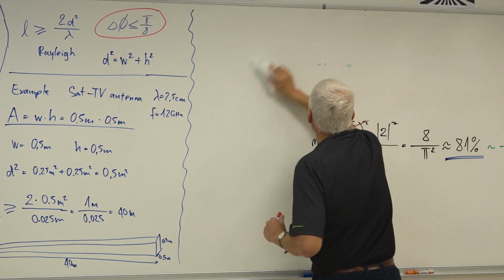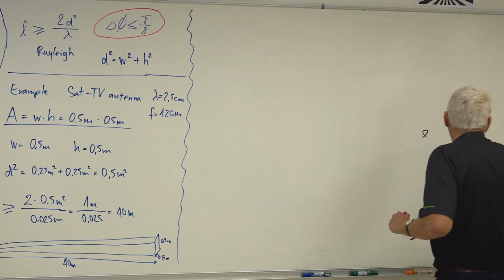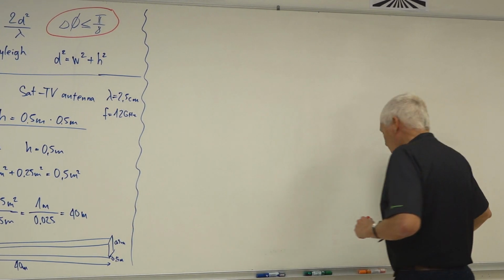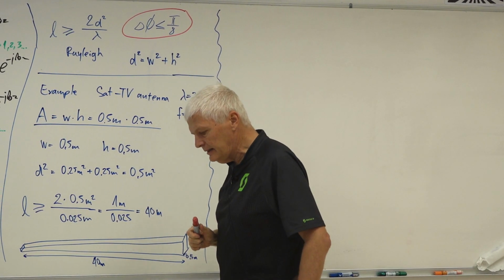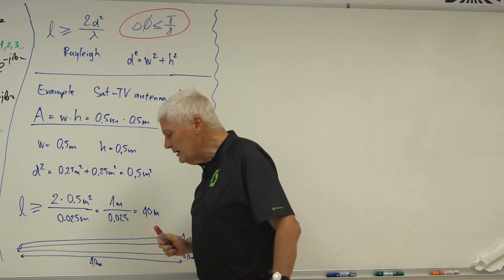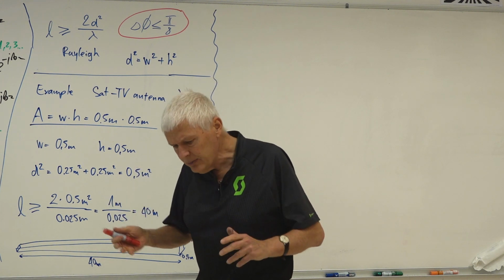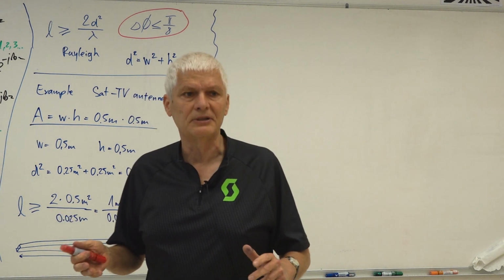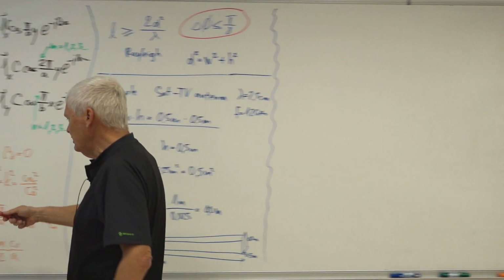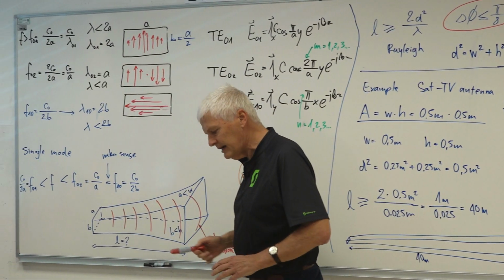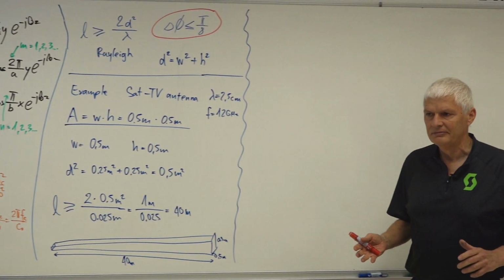And now there is a practical consideration. What length of horn should we use? And what phase error should we tolerate to use the least amount of brass sheet or aluminum sheet to make a certain amount of decibels of gain? Because if I make the horn too short, I have huge phase error, and that kills the gain. If I make the horn too long, I need a huge amount of aluminum sheet.